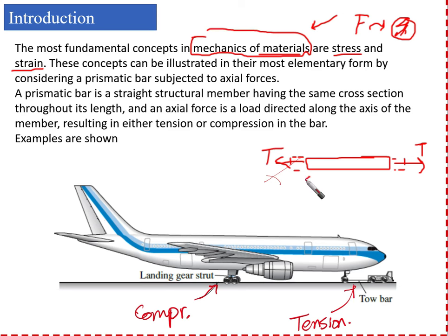That is the amount of elongation with respect to the total length of the element before elongation. If we say it was L before elongation, and after elongation it comes to be L plus delta L, then this small delta L from one side over L is going to give us the strain, as I'm going to elaborate on a little bit later.